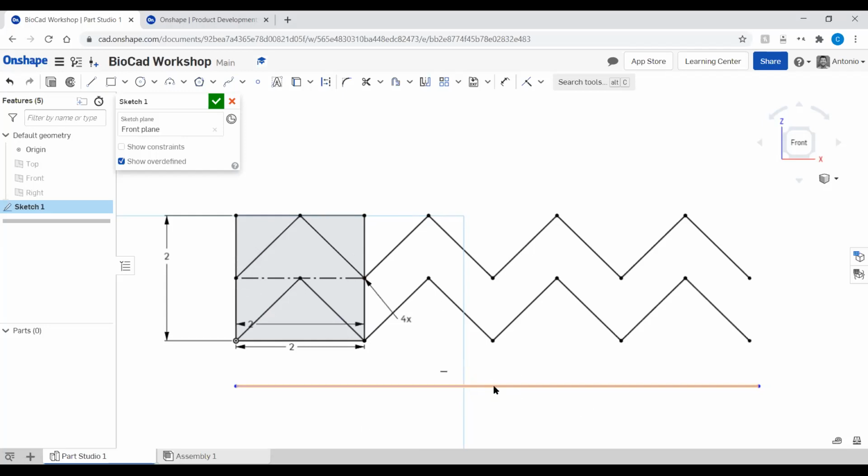What we're going to do is click that line, and then over here in the top, you should see an option that if you hover over it, it says construction. And the keyboard shortcut there is Q. So you can just hit Q or click that button right there, and then you should have a constructed line right there to right here. Now, actually click construction, and then to get rid of it, click away.